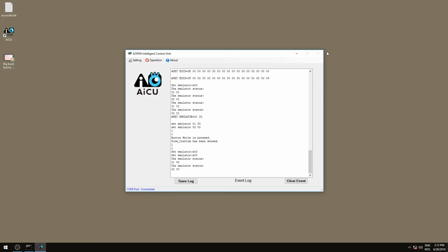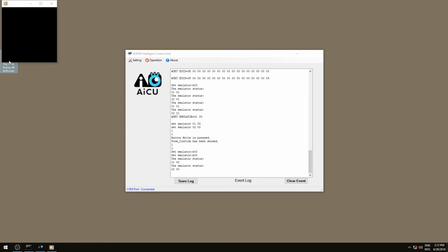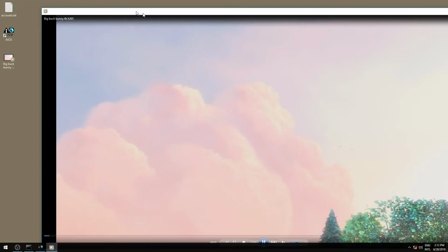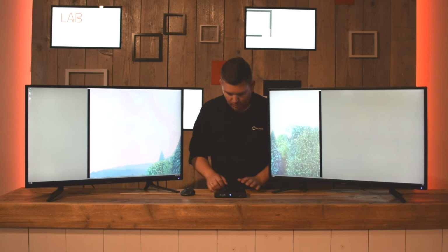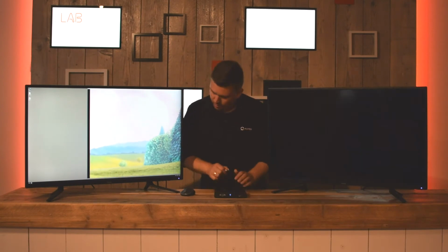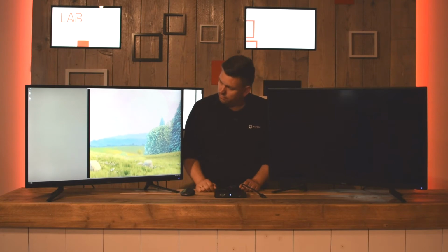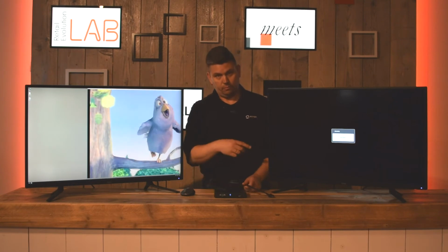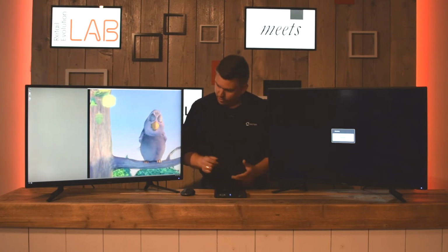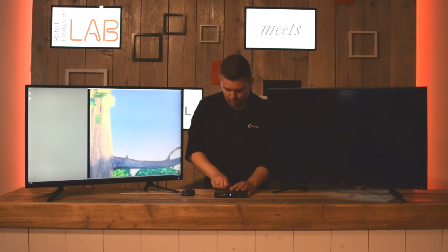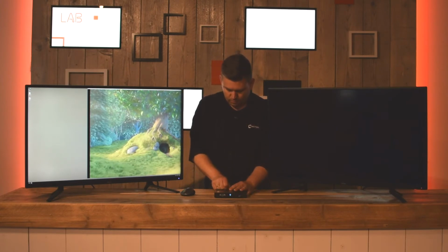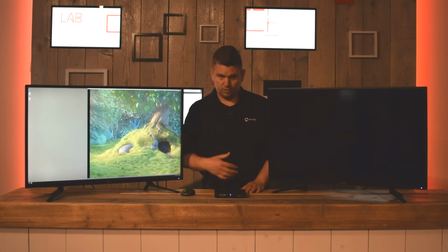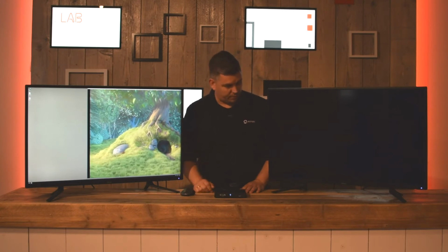Now when we start the video and drag it over to the second screen as well, now when I disconnect the screen, nothing should change. See? Windows is okay with it. It just sees the second monitor via the EDID emulator, and it just continues operating on screen 1. When screen 2 is reattached, it will start up and just continue operation as if nothing happened.